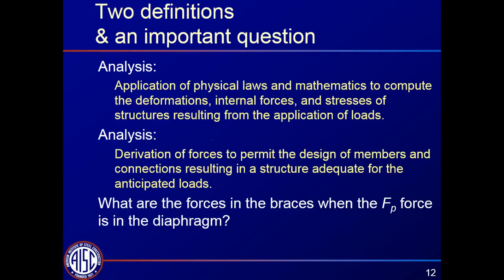I'm just going to say at this point, we can't assume the forces in the braces are zero. That doesn't seem to be an appropriate prediction, and more importantly, it would lead to a design that might fail if there are any significant forces in those braces. So if it's not zero, we have to come up with some answer that we can use in design.